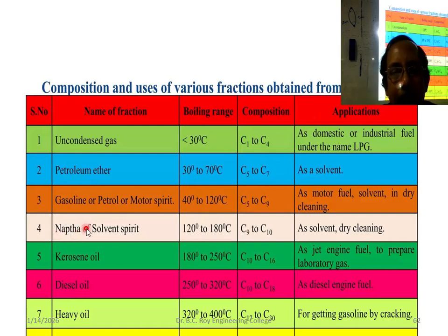Okay, see, then you have naphtha. What is the purpose of naphtha? Naphtha we are cracking to prepare raw material, the monomer for the polymer beads. That is the purpose. That's why the naphtha cracker unit, yesterday I mentioned, at Haldia Petrochemical. This naphtha, of size C9 to C10, is cracked further to produce small fragments, mainly ethylene. Ethylene and propene are our target, because from that we can prepare the polymer. The monomer is ethylene, so we make polyethylene beads.